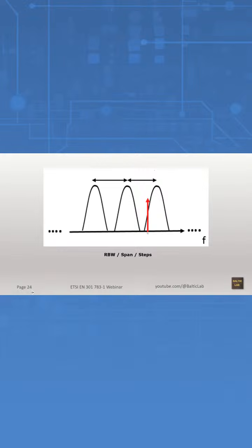Well, that doesn't mean that a signal that's outside of that bound doesn't come through. So if somebody would do the math, the 143.7 something megahertz would be this peak of where the spectrum analyzer thinks it is, and the signal is in our case actually above. So we're getting a false frequency reading and a false amplitude reading. Both are wrong, and this is the number one thing.